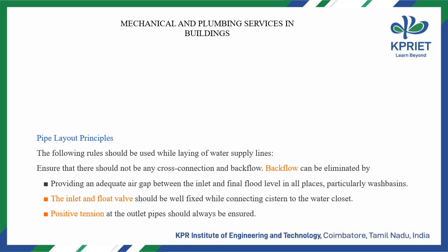Next. Pipe layout principles. The following rules should be used while laying of water supply lines. Ensure that there should not be any cross-connection and backflow. Backflow can be eliminated by providing an adequate air gap between the inlet and final flood level in all places, particularly wash basins. The inlet and float valve should be well fixed while connecting cistern to the water closet.